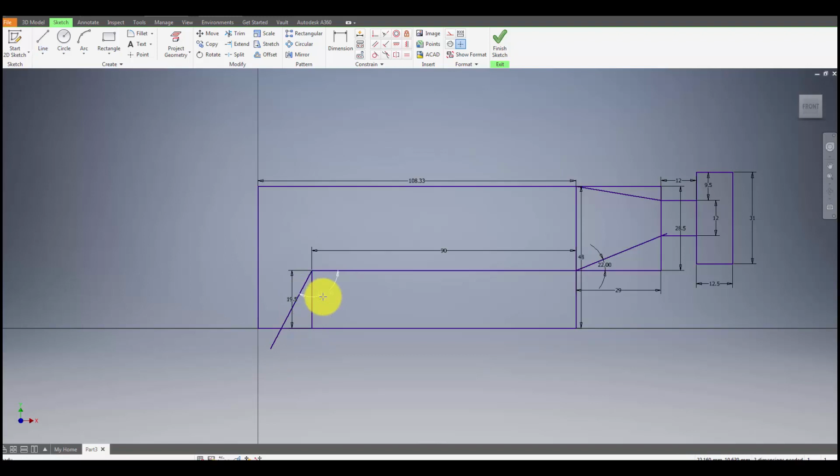Draw a 48mm circle from the datum end. So this size is 48 millimeters. So if I choose the circle, if I simply move slowly down, we can see on the XY coordinates that are being given, X is now 0, and when that Y is at 24, the cursor turns green. Click there and I can drag out that circle, green again, and it fits that perfectly.